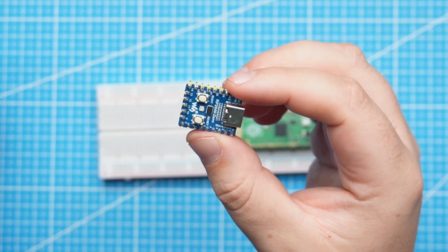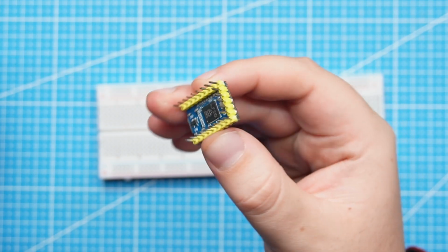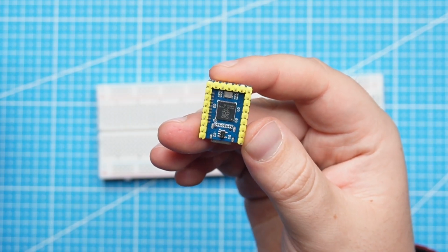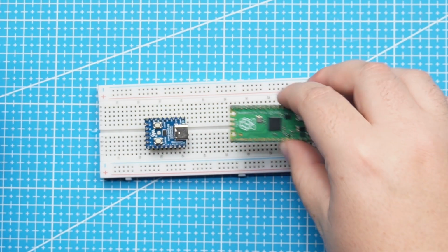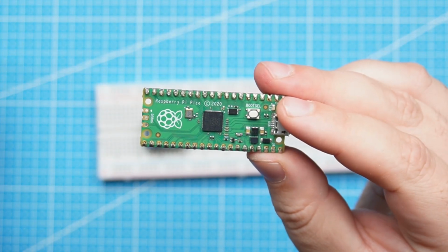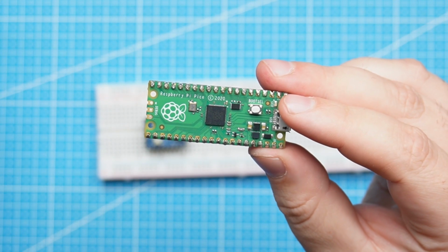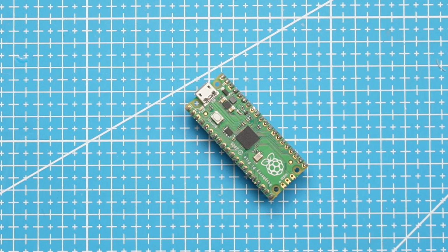The only problem with this microcontroller is that we cannot connect it to the breadboard due to its pin layout. But since this is using the RP2040, we are going to use the Raspberry Pi Pico that we can connect to the breadboard. So the setup for both of them will be the same. In the second video when we make a PCB, there should not be any issue, as the GPIO pins and everything would stay the same for both of them. Let's set up our Raspberry Pi Pico.